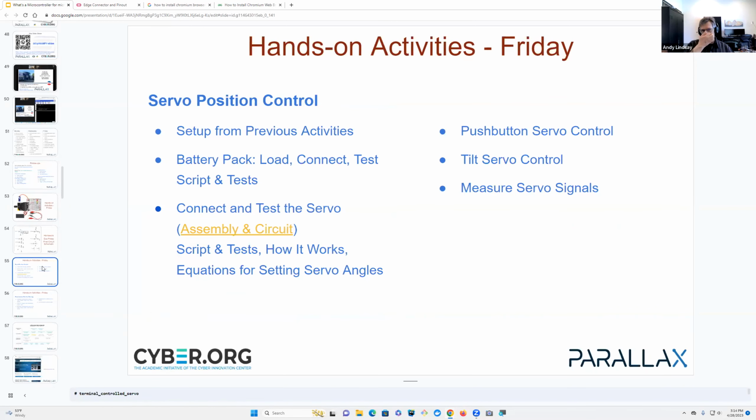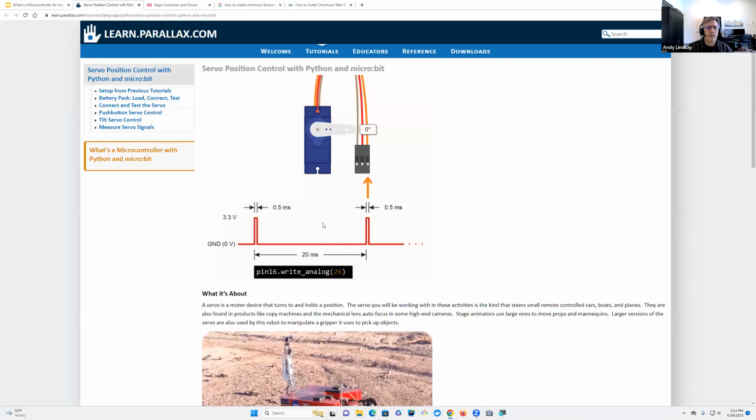First thing about the servo, a servo is a motor that you can use to move to certain positions. So looking here, you'll see that there's a signal going to the servo from the microbit, and depending on the signal, the servo will turn to and hold, and you can even press lightly against this. It's called a horn, this little armature. The servo horn is the common reference. And it looks kind of like a horn, if you think about it, the single armature at any rate. And so based on the signal that gets delivered 50 times a second, whether it's very short like you see now, or the high signal lasts longer and progressively longer, you'll see that the servo turns to and holds a further counterclockwise position.